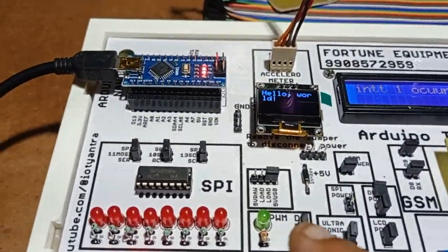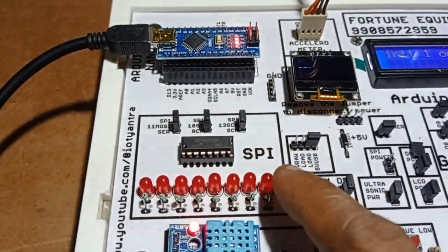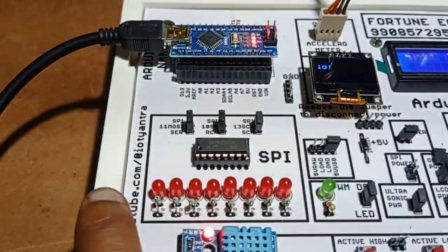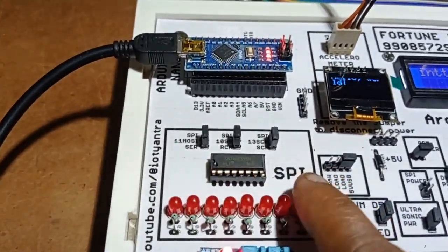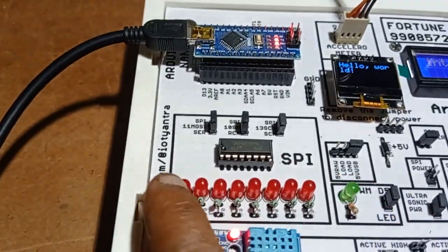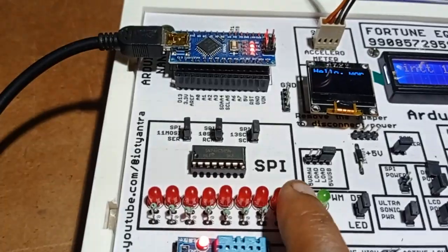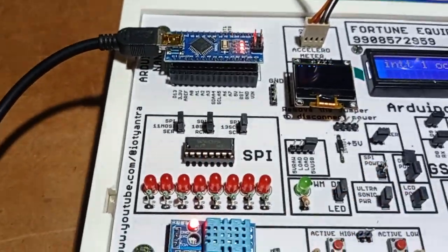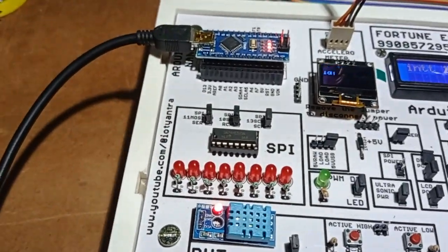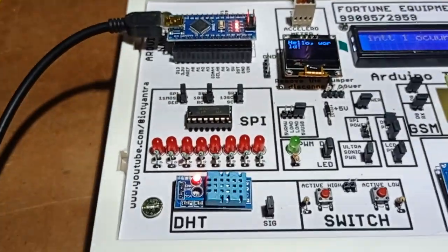So we are going to interface this with the help of code, and we are going to create LED patterns. Actually it's 8-bit, so with these 8 bits you can have numbers 0 to 255. This is LSB and this is MSB. So from LSB to MSB you can print 0 to 255. All LEDs glowing is 255, nothing glowing is 0. You can just send any desired number, or you can create animations like scrolling effects, moving effects, etc. using this particular register.